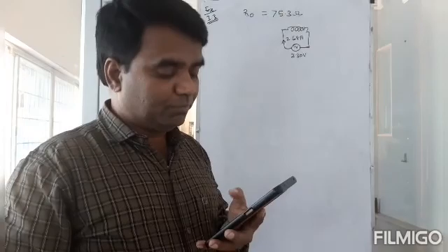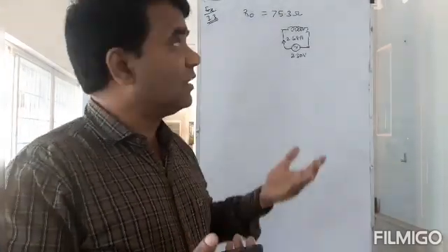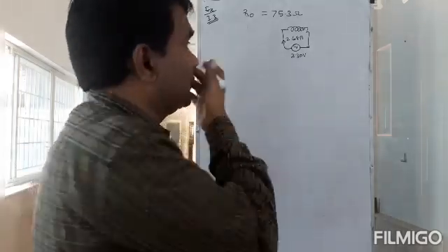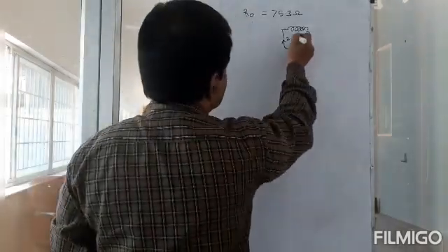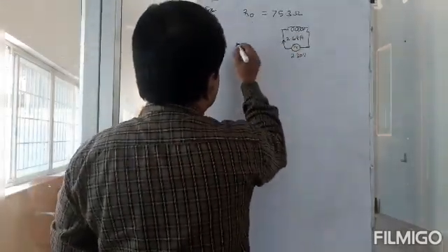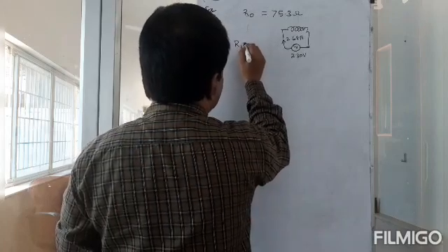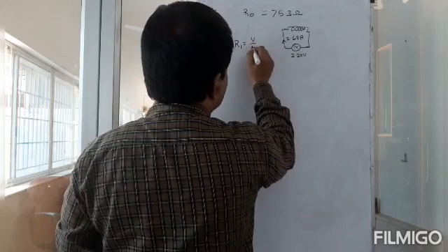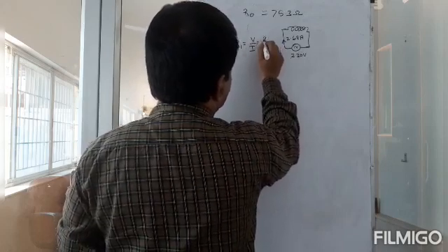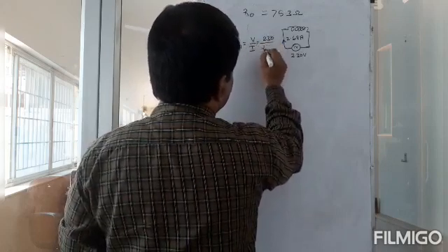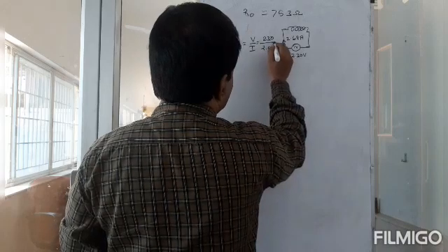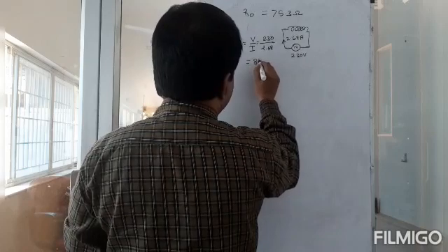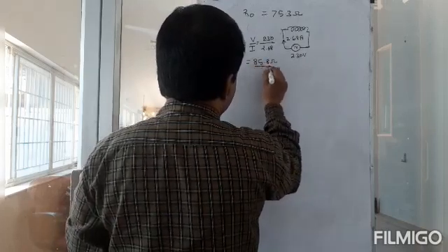That's the question. To do that, first of all, you need to find the resistance of it, right? So I have 230 volts and 2.68 amperes. Then what is the new resistance of it? It's going to be equal to V by I. So that is 230 by 2.68 amperes. So that gives me 85.8 ohms.